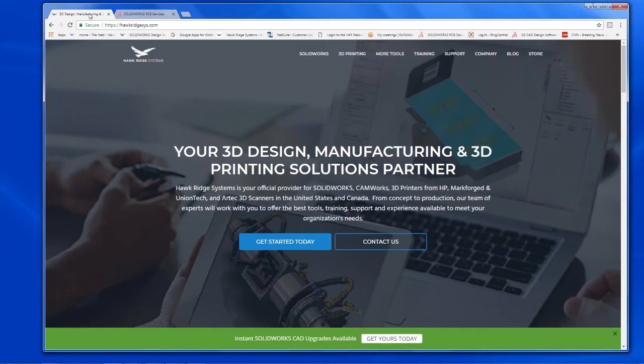How does this compare to using Altium with SOLIDWORKS? Great question, Aaron. So the collaboration portion that I showed you is exactly the same between SOLIDWORKS PCB and Altium Designer. So the modifications that I did in SOLIDWORKS, the movement of the RF connector, the association of the collaborative PCB assembly to the overall product chassis with the additional PCB, that is no different between Altium and SOLIDWORKS PCB.